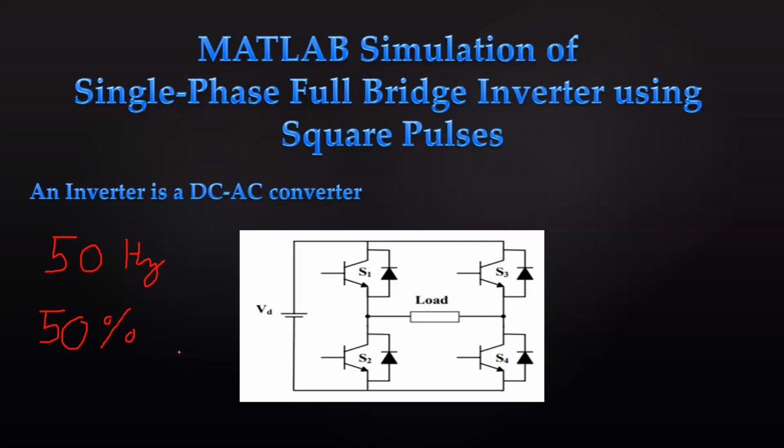We have to make sure that our output is equal and opposite, that is, it covers the same area in the positive section as in the negative section. Then only we can call it an alternating supply, right? So at what time will we trigger them? The first IGBT or MOSFET switch as well as the fourth MOSFET switch, we will trigger simultaneously.